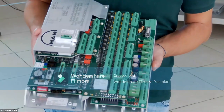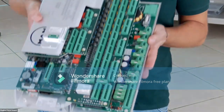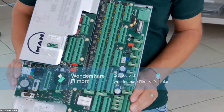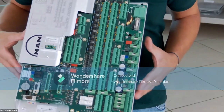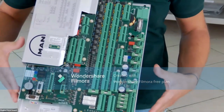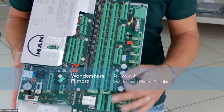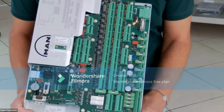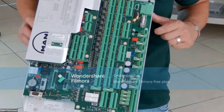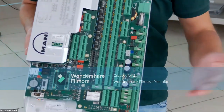Yes. Good. So we discussed the position of the dip switches, and now you take this controller and install it back in its place. Gentlemen, at installation, you connect all the wires in reverse order. So you connect the connectors, the plugs, the ID key, the network and power source. When you connect the power source, automatically the LED will start to blink between two red lights and one green for around 5 seconds.